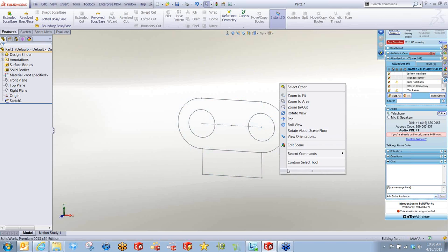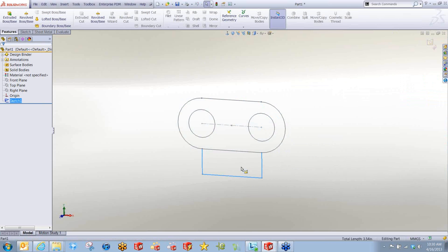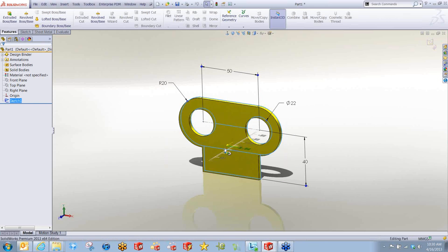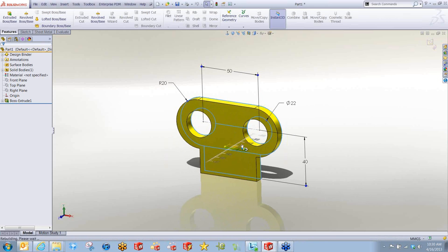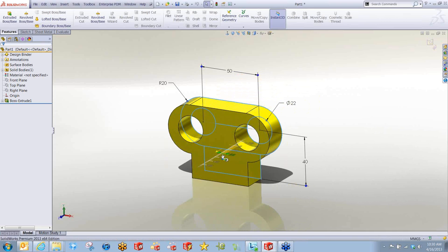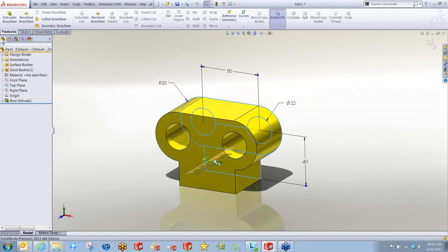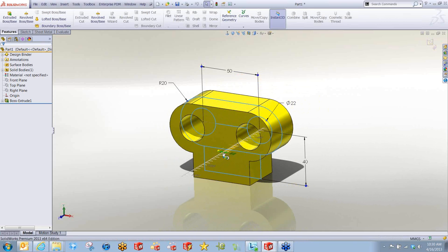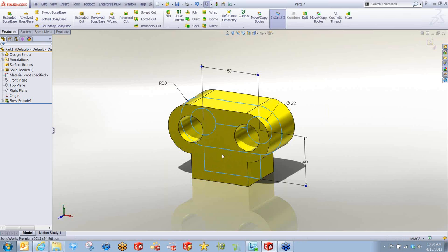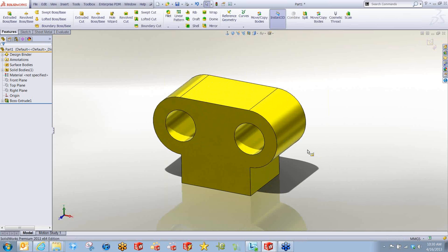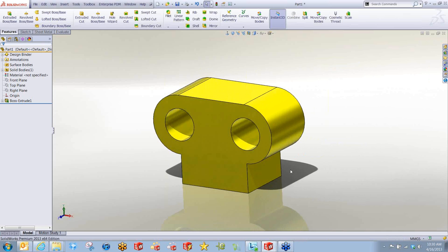All right, so now that I've got my 2D sketch drawn up, I can start selecting the contours that I would like to extrude out or give material to. So we'll grab these two, and then I can use my on-screen ruler to snap to. We can even add a little more intelligence to the model on the fly. Like here I want symmetry.